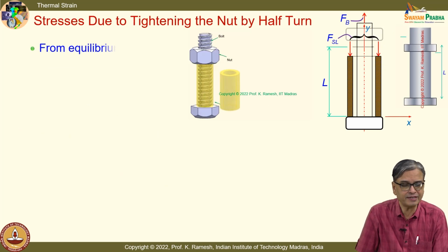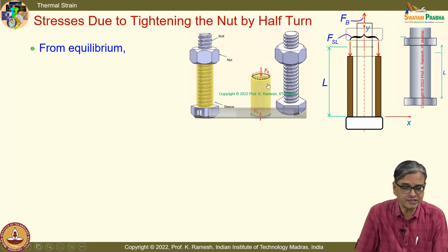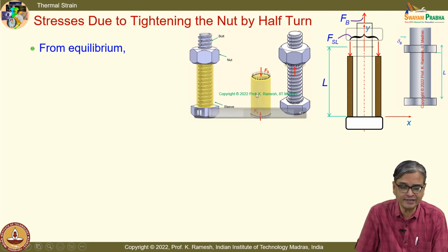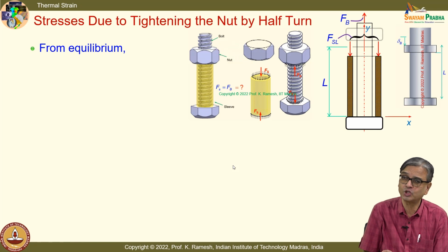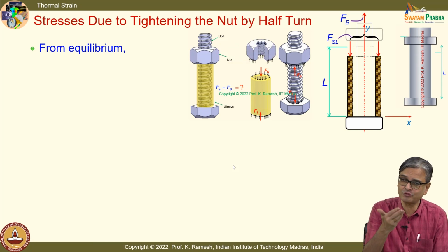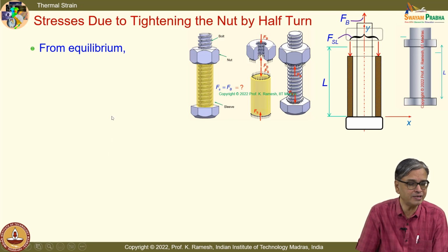That also we have seen. When I have a bolt and nut tightened, we have said the forces on the sleeve and forces on the bolt should be identical, but we do not know how to calculate based on statics. You need to bring in deformation into the picture, and in this case we have first looked at the deformation, wrote the equation, and this equation is simple and straightforward.